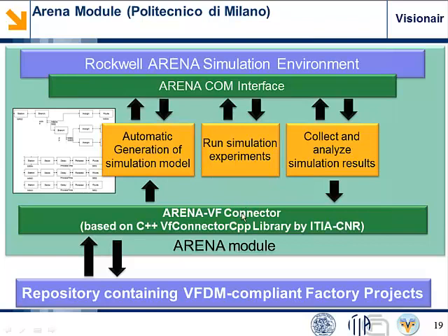And then we read here, and what do we do? Well, first we understand how the system has been designed, and grounding on this, we automatically generate a simulation model representing the behavior of the manufacturing system within the data repository. Given this, we build it in Arena, and then we run the simulation within Arena.